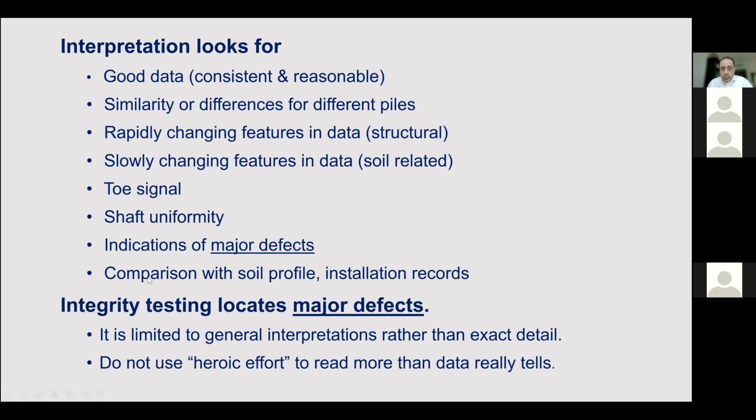It's always good to compare with the soil profile and the installation records, especially if you have any doubts or if you think there's something wrong in the signal. It is good practice to always have a look at the soil profile, and at anything in the installation record that can give rise to some doubts.